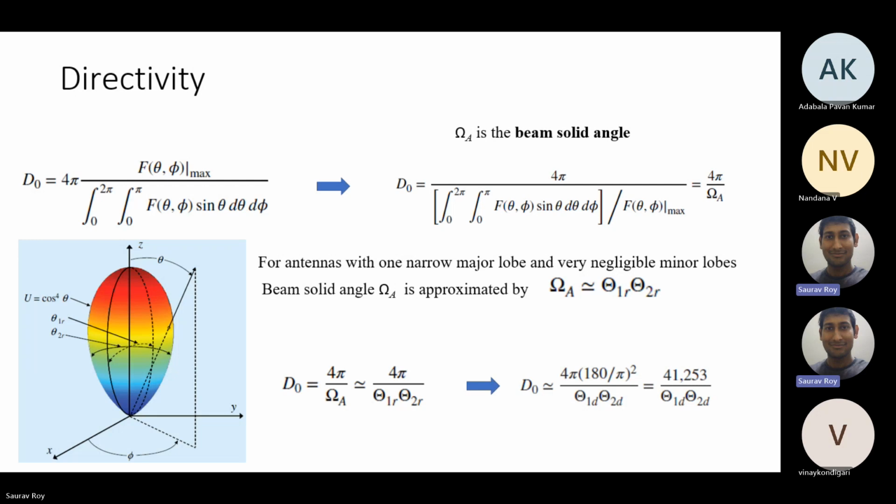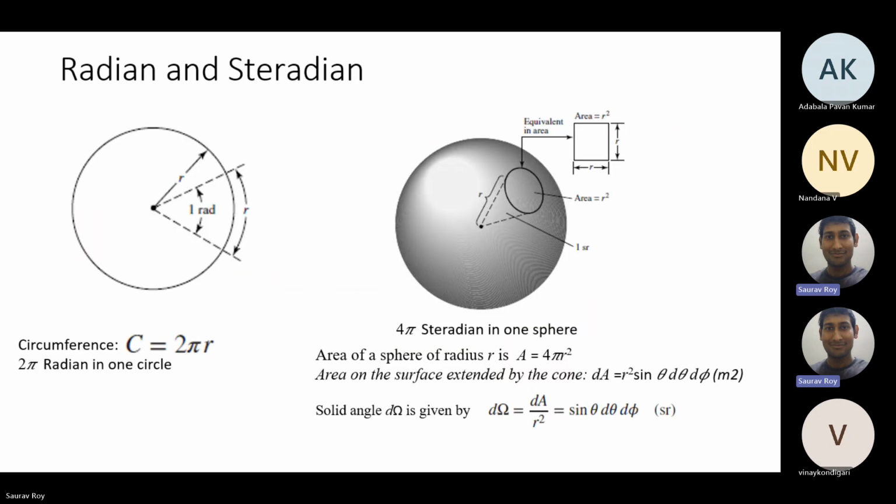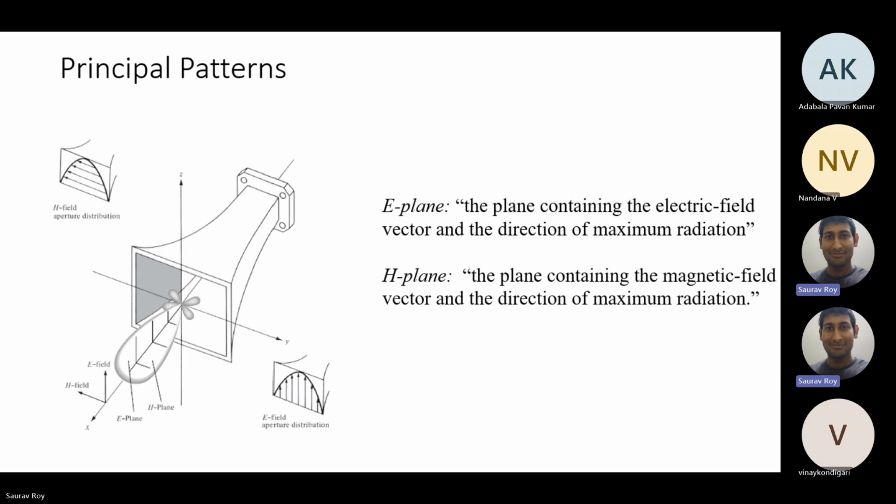If you remember, I will go back. I don't know how we forgot it so quickly. I discussed this only last week. That's why it's relevant and very important. All the antenna patterns will generally be measured in the E plane and H plane. We cannot measure all 3D angles. In 3D, you can have many angles. We generally take pattern measurements in two perpendicular planes, the E plane and the H plane, and they are perpendicular.